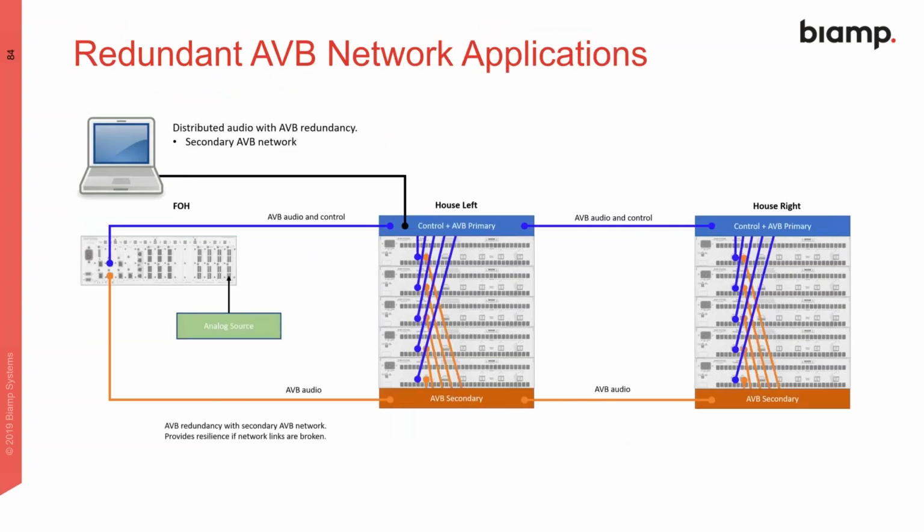We also support the primary secondary ports of the server I/O and the server. On server I/O and server, we create AVB streams on the primary port. They also create a second set of AVB streams on the secondary that are always present, running in parallel with the ones on the primary. We seldom use those, but in this application, we can.